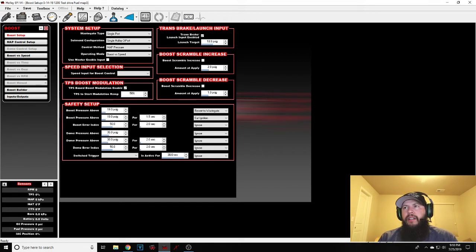Instead of using a magnetic sensor that's going to pick up on metal high points, it'll be a sensor that's going to pick up off of magnets. So I think that's probably the direction that we'll end up going with it, unless I grind down the faces of the bolts and make sure that it's consistent, having to be within like 30 to 40 thousandths. I don't think that's the way to go. So since I know all of those bolts are identical size, they're just not the shape that I want them, I'll probably put a magnet on each of them, and that'll be my 6 pickup points.